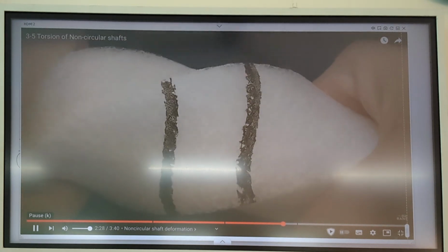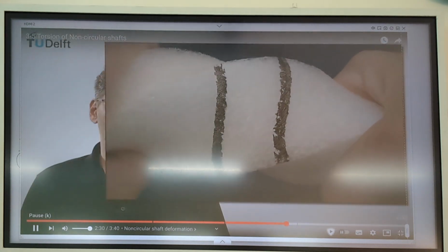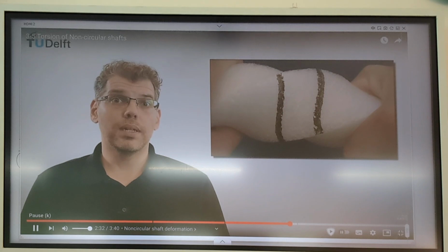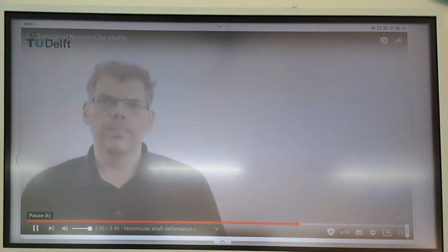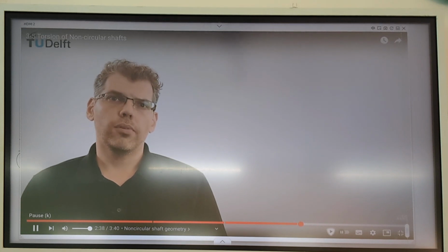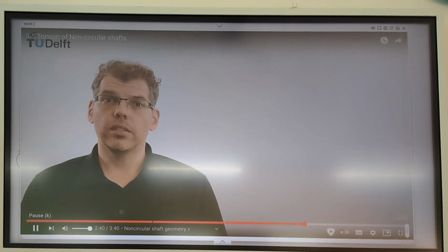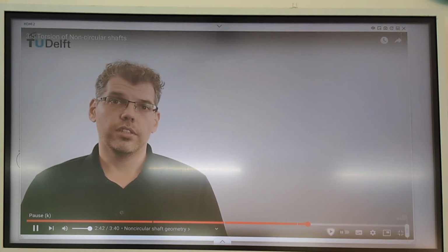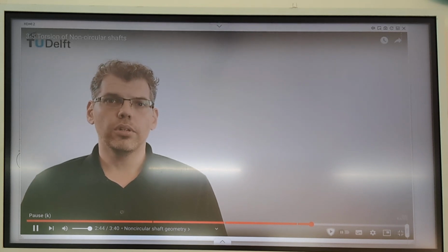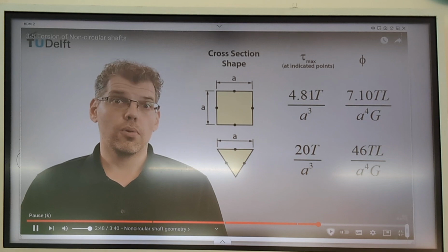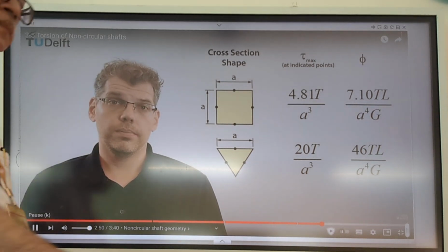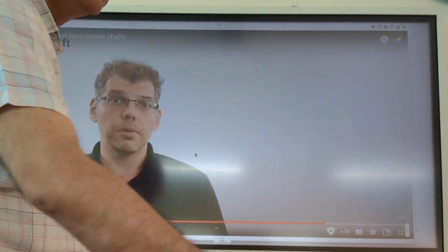This is an indication that the assumption that we made for circular shafts, that planes remain plane, is no longer valid. It is possible to derive formulas for the shear stress and angle of twist for non-circular shafts, and many engineering handbooks have tabulated results, such as the one shown here, for specific geometries. However, for the same cross...